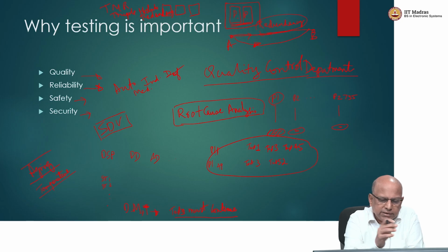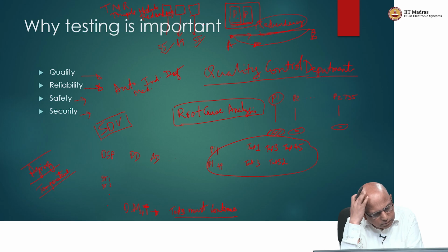If the answer given by the first processor is let us say 55, this is saying 49 and this is saying 55, then you take this as the correct answer. So, voting is used, 2 out of 3.